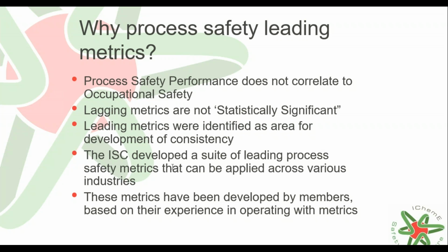If you've got a particularly nasty service, like waxy asphaltene crude oil, you need to spend a lot of time conditioning the sensing lines and the PSV so that you don't put a lot of wear and tear on it. So I think having the right level of understanding and expertise within the operational group of what you're actually trying to achieve. But if you've also got the luxury, if you've got an operating plant, then you've also got a good rich history of actual performance.